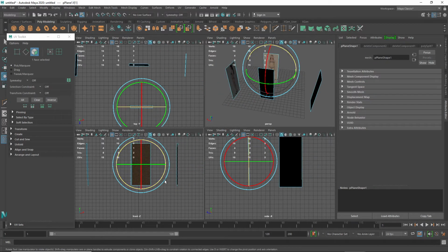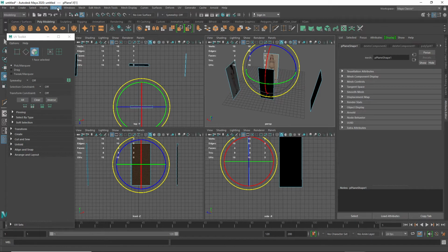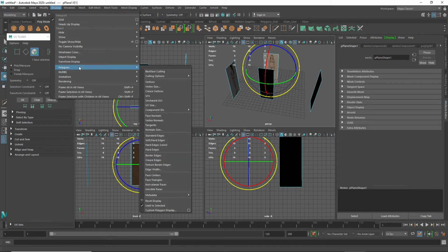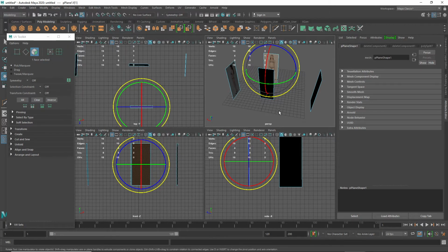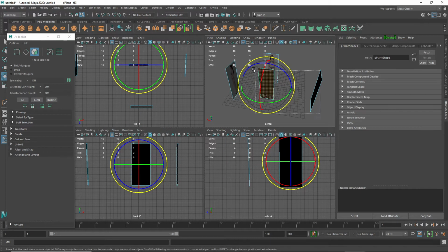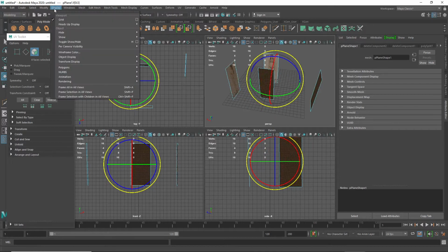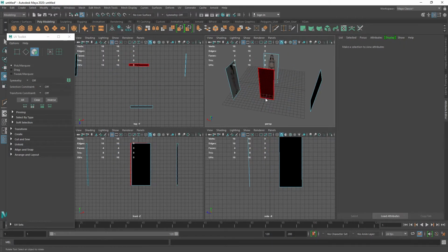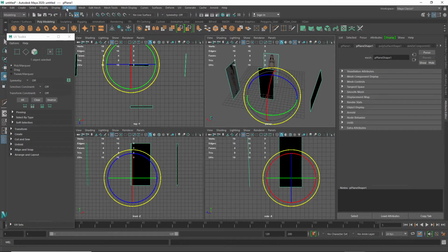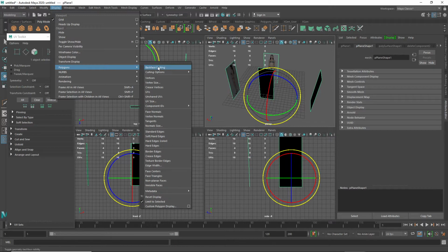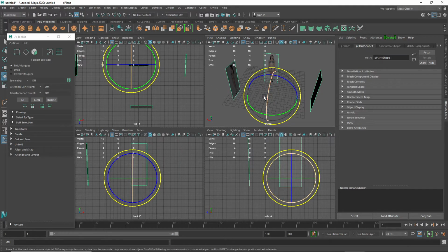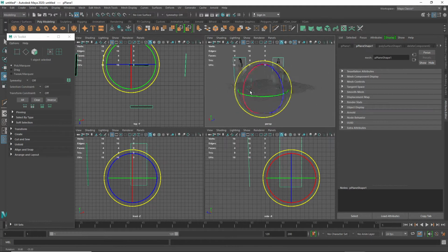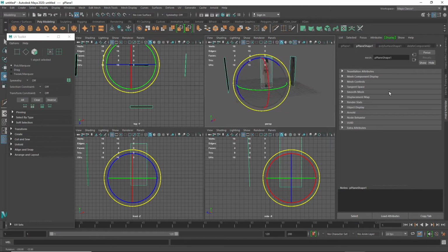The next thing I'm going to do is I'm going to go here. With my object selected, I'm going to display polygons and backface culling. Actually, let's select display polygons and backface culling. Now, what backface culling should do, I think it might have to be in object mode. What backface culling does is basically delete the back side of that. So it's like a one-way mirror. Okay.